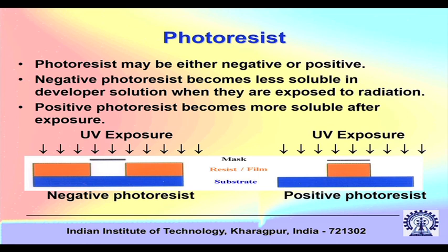Now on the SiO2 layer, we coat a photoresist, which is the next level of coating, before we shine a light source on the entire system, masked by the mask with certain patterns. The photoresist is deposited by a process called spin coating. There is a device called a spin coater which deposits a thin film of the photoresist on the substrate.